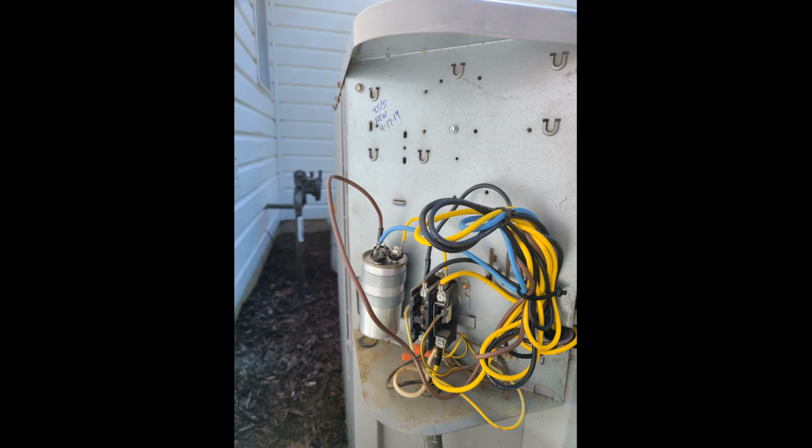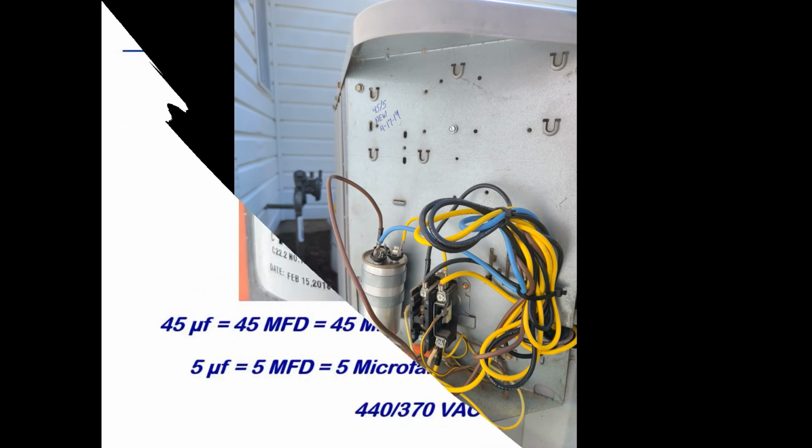Consequently, I recommend that you purchase a spare capacitor and store it in your basement or garage so you can immediately replace the capacitor yourself for approximately $20 to $30, as opposed to having to wait 1 or 2 days for an HVAC contractor to replace it for $200 to $400.